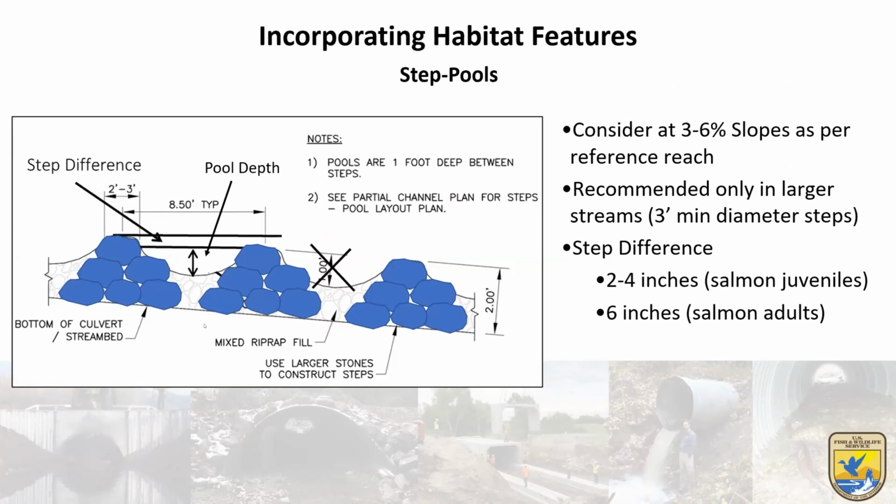When we talk then and moving steeper, we're looking at step pools. With rocky riffles, you can consider them all the way from 0 up to 6% slopes or so. And then it becomes more of a cascade system, which is an even rocky ramp in some ways. But step pools are present in a very specific slope range within the geomorphic environment.